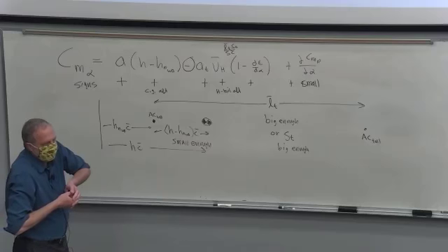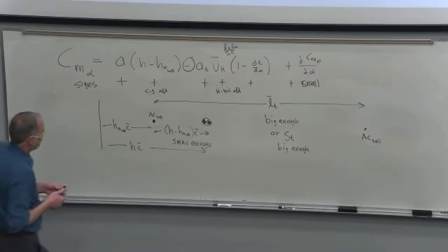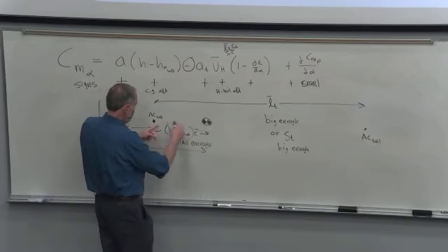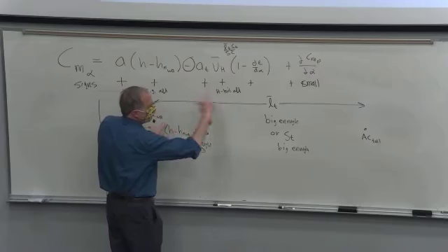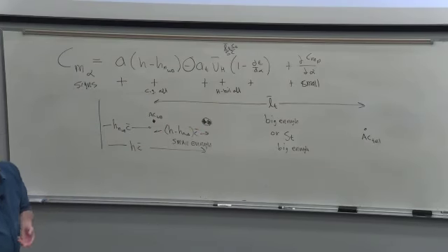So it's real easy to do. You build your airplane, you find out where the CG is, and then you just keep making the tail bigger and farther back until it becomes stable. But if you put too much tail back there and you put too big of a tail boom, you have to have all this structure in there to carry it, right? So there's kind of an optimization you want to go through. You want to get your CG small here so that you don't have to have that huge tail way back there, for efficiency and aerodynamics and just structures and building it.